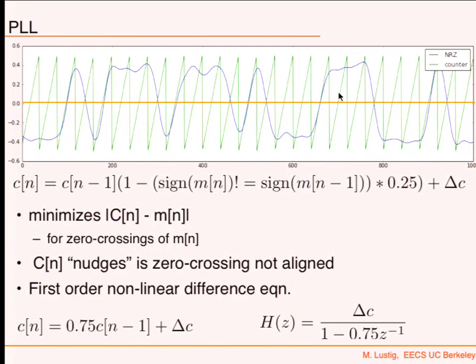If it's a negative number, though, and we just multiply by A, aren't they actually nudging it? It still nudges it to the right position. That's the nice thing about it. If it's negative, it still nudges it towards 0. So that's another thing for stability. But this is an IIR filter. If you think about it, it's nonlinear, but it's kind of like an IIR filter.